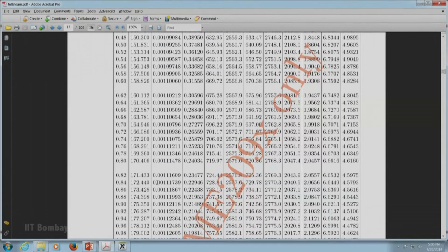As is known to us, the process is a constant pressure process, that means at point 2 also the pressure is 6.5 bar. So, going to 550 degree centigrade, we check Tsat at 6.5 bar, compare that Tsat value to 550 degree centigrade and get the state of point 2. So, first look at 6.5 bar, which is 0.65 MPa. Again I will have to interpolate between 0.64 and 0.66 and get those values here. Similarly, I will compare the temperature.